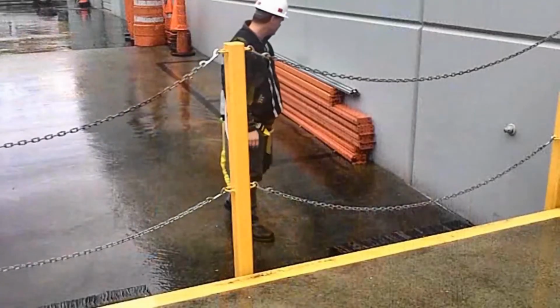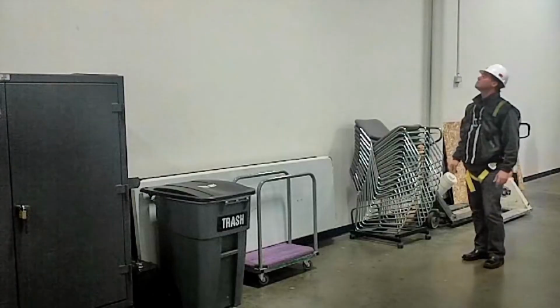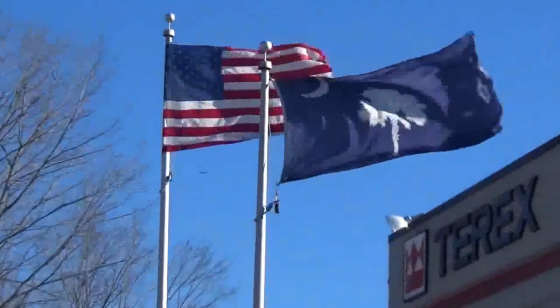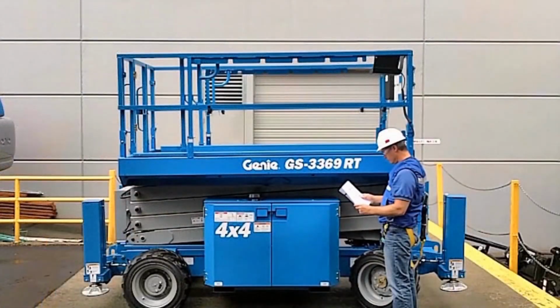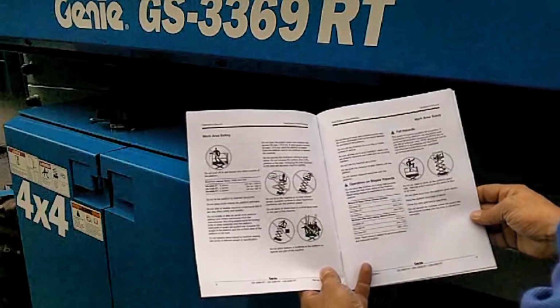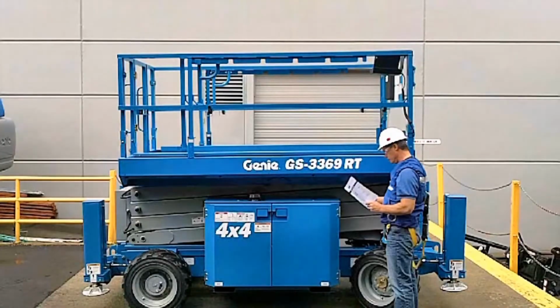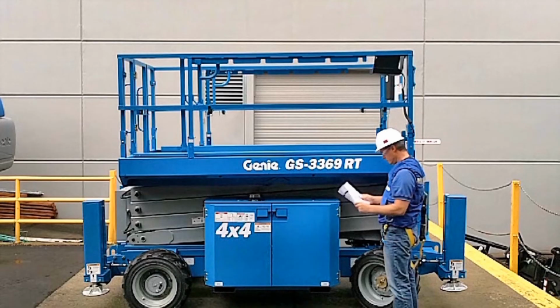Keep your eyes open for drop-offs and holes, floor obstructions and hazardous locations, overhead obstructions, electrical conductors, and wind and unsafe weather conditions. Other workplace hazards are listed in the operator's manual. There may be others, so always make sure that you have identified all potential hazards and know how to avoid them before moving the MEWP into the workplace. It is also important to note that you, as an operator, have an obligation to inform the user or owner if a work environment contains even one thing that will prevent you from safely doing your job.